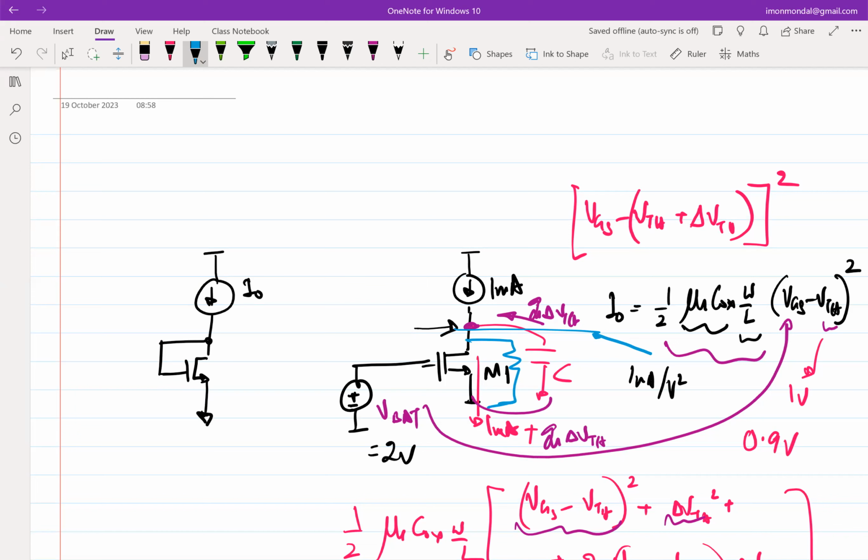So this will settle somewhere, and wherever it gets steadied will be the case in which the transistor is in the linear region. The moot point I'm trying to make is that even though this mathematical equation tells you that one current source and one battery will help you bias the transistor in saturation, given that you do your calculations right, in reality it will not.